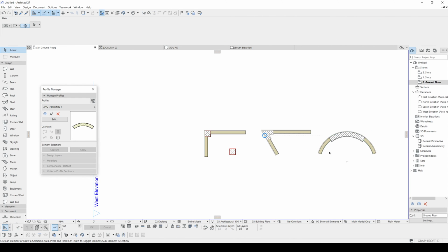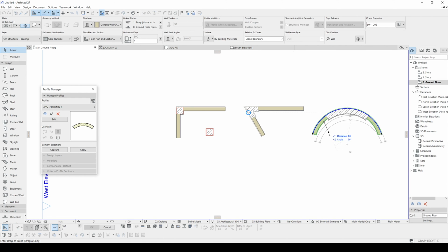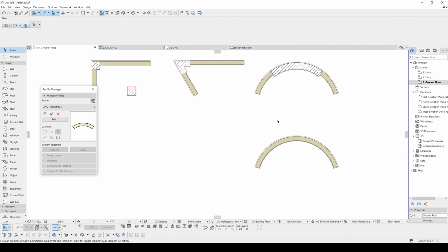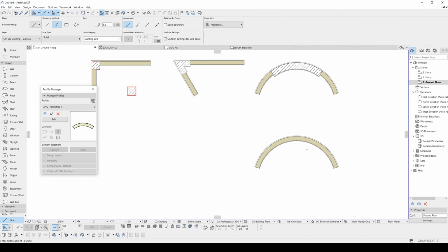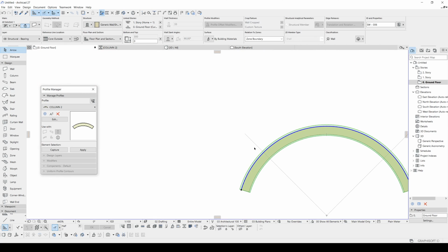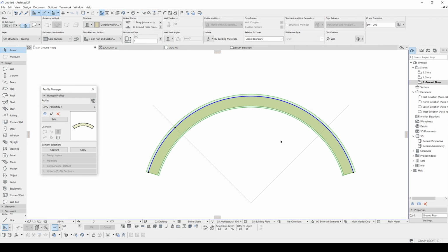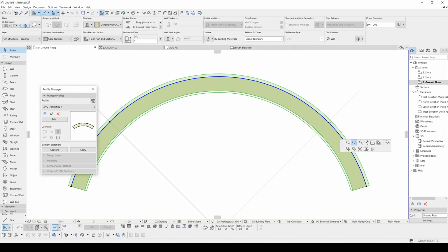By the way, for this method I want to show you a different way. Let's duplicate this wall. And let's say that our borders were something like this. When we see this, we will click our wall and then we will split this. We will click this intersection point and we will click this insert new node. Same will happen to here.